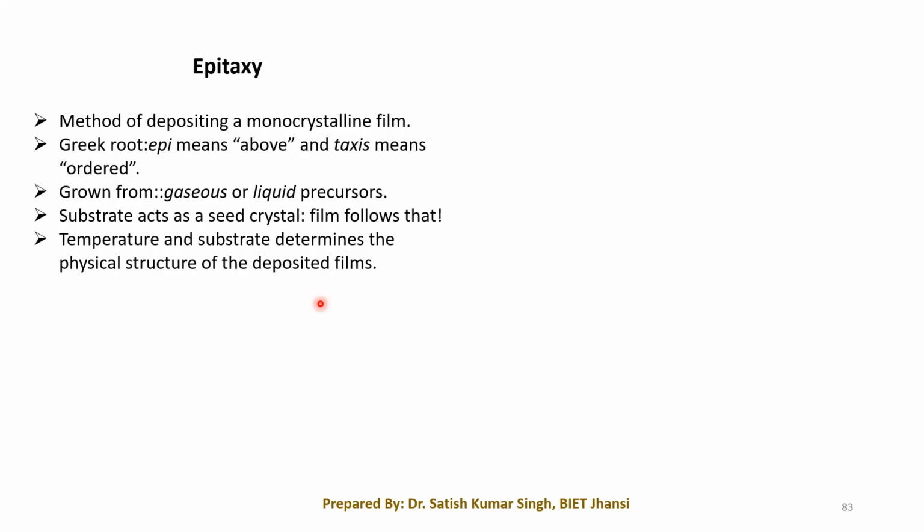First of all, you can understand that we have a substrate, and we get the wafers from the ingot. During the ingot formation, or the pulling of the crystal, we add a certain type of impurities into the melt to get a particular type of substrate.